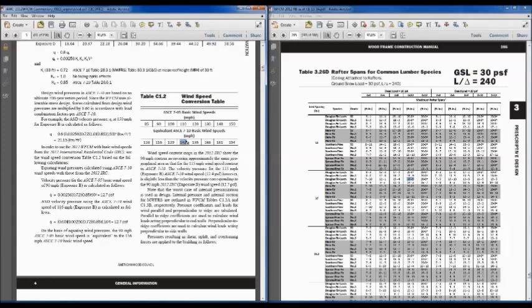So for our example here in the wood frame construction manual, when we converted this over from the ASCE 7-05, we were at 120. We went to ASCE 7-10, and so I rounded up to 160 instead of rounding down to 150. A lot of parts of the country have rounded down to 150. So this little table here is comparable to what's in the IRC. It's the wind speed conversion table. I know it's confusing, but everything in the wood frame construction manual is based on ASCE 7-10 wind speeds, and for our example, we're right here between these two. We're at 160, which is between the old 120 and 130, if that helps you at all. So these are all wind speeds based on ASCE 7-10.